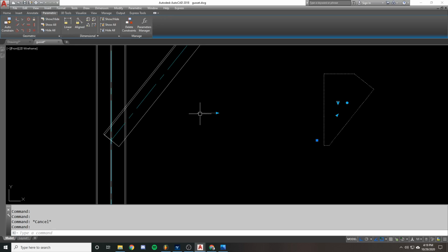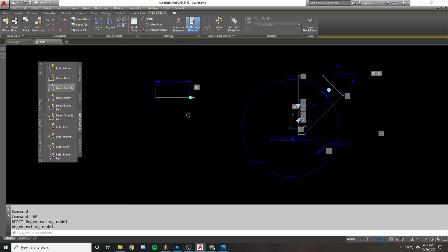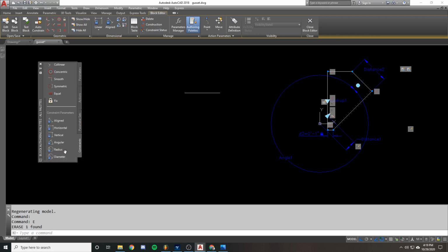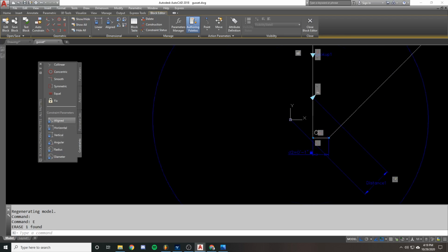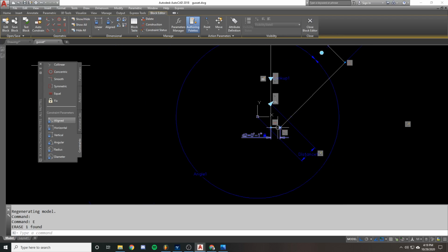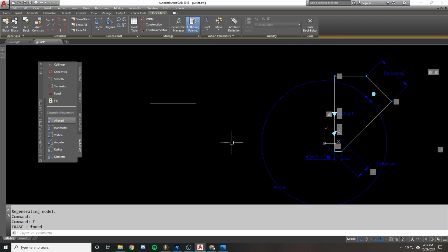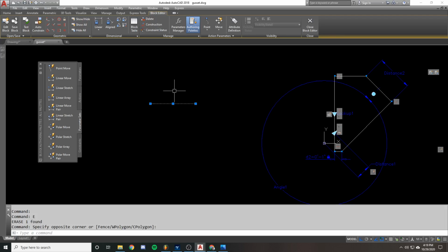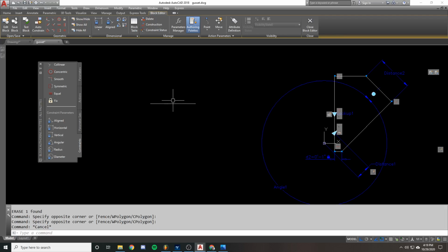There is a big difference, though. The difference is that when you're using a dimensional constraint with geometric constraints, I can tell it to always set this at 1 inch by saying this D2 equals 1 inch. A stretch parameter could not do that. So a dimensional constraint can act as a linear stretch with one grip. It can act like that. But typically you're using it as a constraint to constrain the length of a line. But the more interesting thing in here is that if I do, let's say I copy this down, okay?